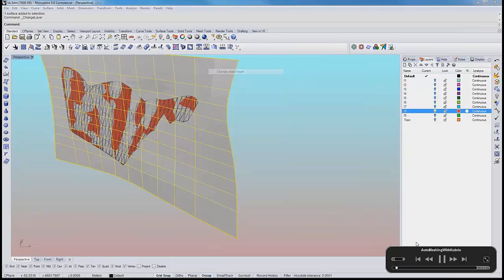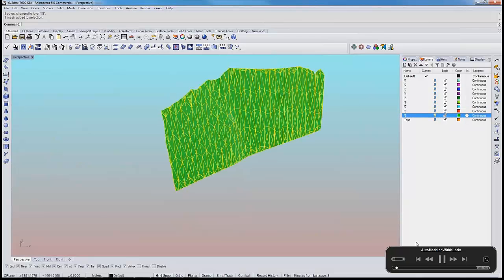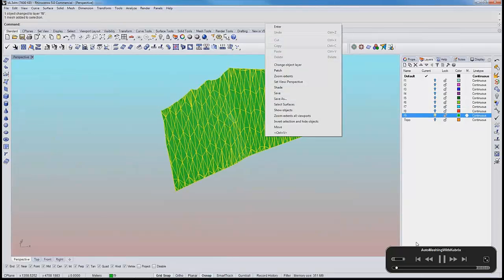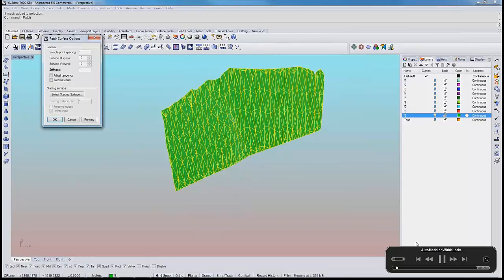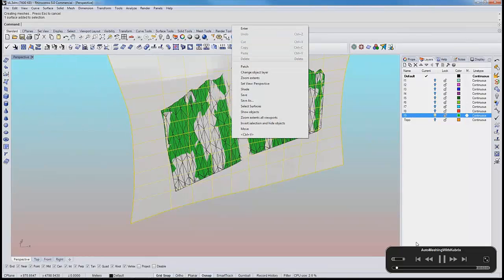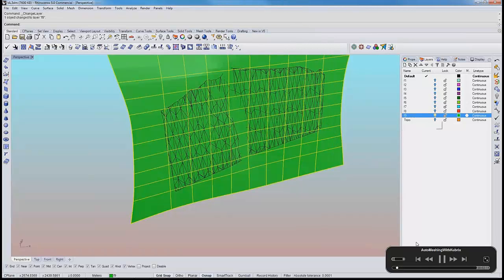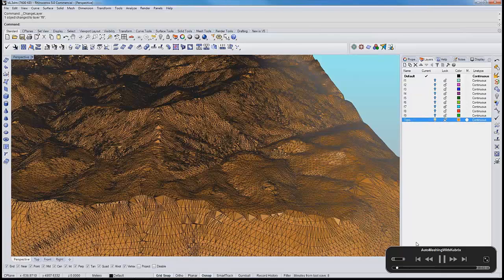Here I'm using the same resolution in the U and V spans, and now I deal with surface number F9, and I again turn that into a patch and make sure that each patch goes into the layer where this fault was located. Again, this is going to be a tutorial that will be shortly available.